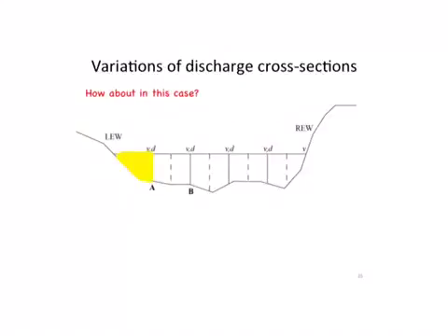And so now the way that we would write this is, I have to change my pen size again. Okay, so now the way that we would write this would be Q equals, let's just do an incremental velocity between A and B. So we're talking about this polygon that I'm outlining in black. Okay. So the incremental discharge through A and B would be equal to just the average of the velocity measured at point A plus the velocity measured at point B